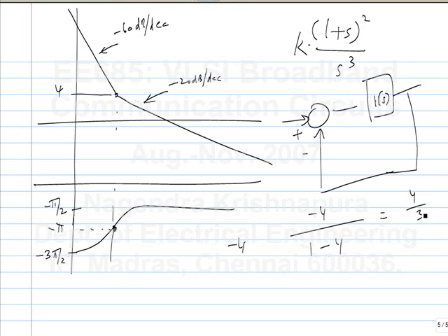The question was, let's say you have a 20 dB per decade slope at the unity gain crossing, but you have many poles and zeros before that. It is possible to have a phase shift of pi, but a gain of more than 1. Is that a stable system? The answer is it is a stable system.